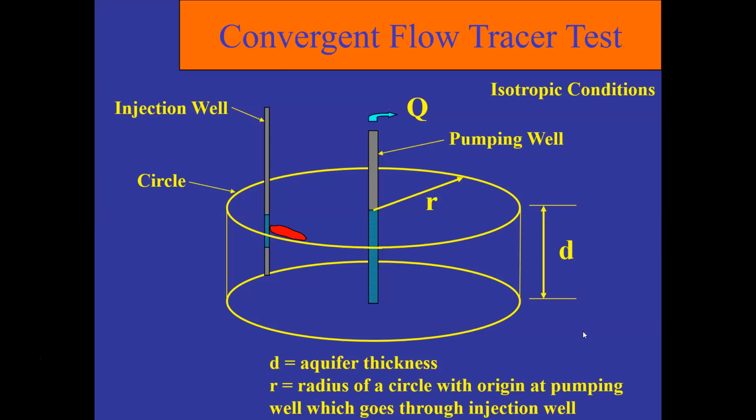Okay. What are the units of anisotropy, and how is it defined in the context of the 8-hour tests performed? Well, anisotropy is defined as a ratio. It's the ratio of hydraulic conductivity in the K max direction, that would be in feet per day, over the K min, the minimum hydraulic conductivity, which is often orthogonal to the maximum. So it's feet per day over feet per day, so it's unitless. You would just say the anisotropy is 100. It's a ratio of the K max to the K min.